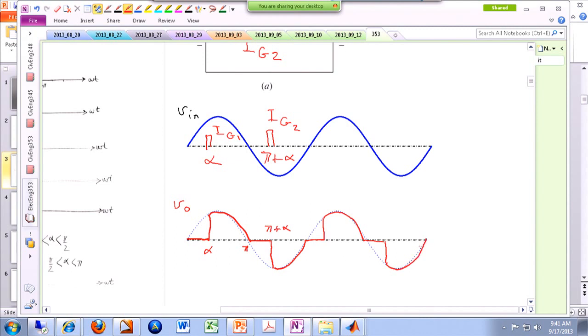So we will be generating some sort of a waveform like this on the output side, which means we are chopping off part of the input voltage basically. As you can see, the output voltage is not DC anymore, and we don't care because our load is a resistive load and it is just supposed to generate heat, and we just want to control the amount of power or the heat that is generated. So very, very simple. So this is how it actually works.